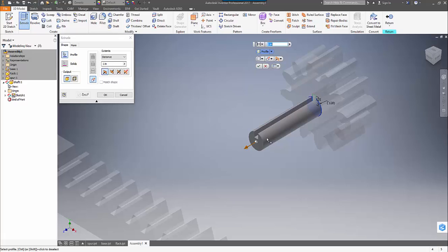And if it doesn't select properly, or if it gives you an error that it's an open connection, then there is always this little red cross up at the top, or it will show up on the extrude command, usually down here in the bottom. And you can use that to help diagnose what the potential issue might be. And usually it's an open loop. You didn't get all the dots connected when you created the object. So right now we'll go ahead and extrude this 3 inches.